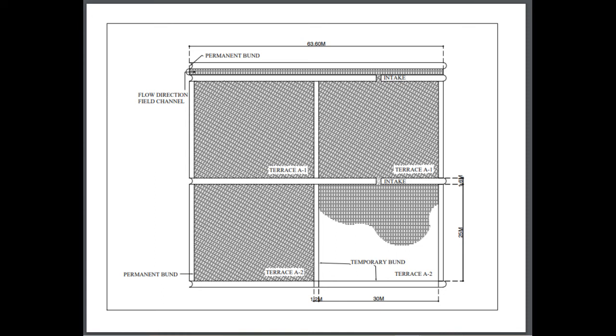So each bay is irrigated in turn using a combination of drainage water from the previous bay and continuing inflow from the supply channel. Successful operation of these systems is reliant on a sufficient elevation drop between successive bays.